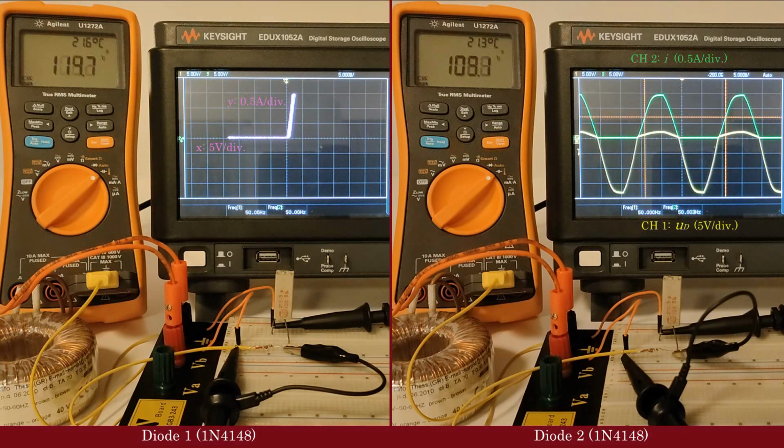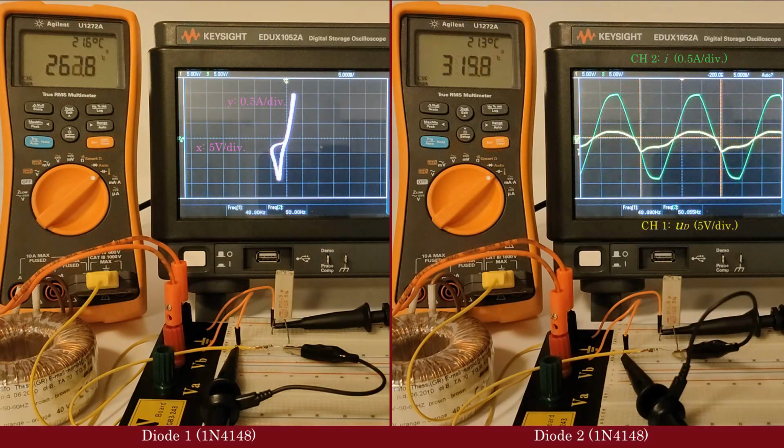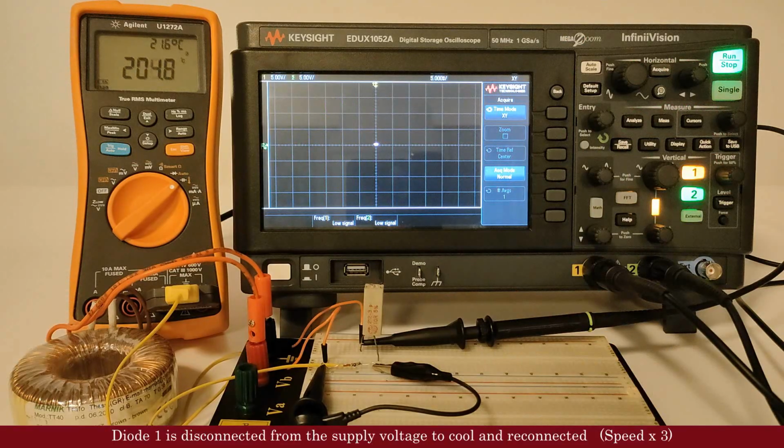Power consumption is excessive. As a result, the diode overheats and eventually breaks down. The diode can arbitrarily open or short circuit during overheating. In the cases shown, both diodes are short-circuited. In some cases, the diode can work normally after overheating.